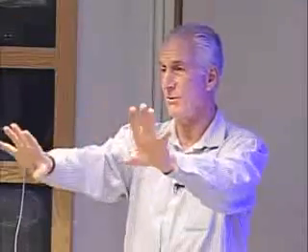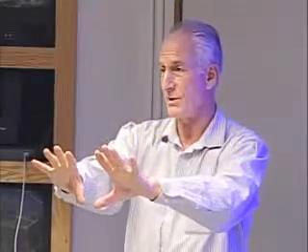So yeah, the forward center cockpit is not used very much when you're on orbit. Overhead panels is mostly OMS and RCS, and then electrical stuff is over the right, and environmental control is over on the left. And so when you're docking with a gear or something like that, the pilot looks out the back.